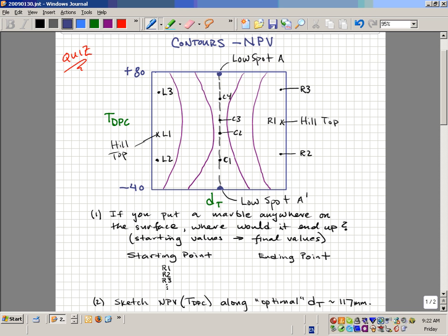But we have to recognize that when we push the solver button, it's going to give us an answer, and the answer may very well not be the real answer we want. Or we have to make a decision that these two are equally valid optima. If we're making negotiations with the Germans about a gas contract, about selling gas from this field, we're actually doing engineering. We have to understand what the solver is giving us when we push the button. Can we rely on it? Is it giving us maybe one of multiple solutions, and so forth?